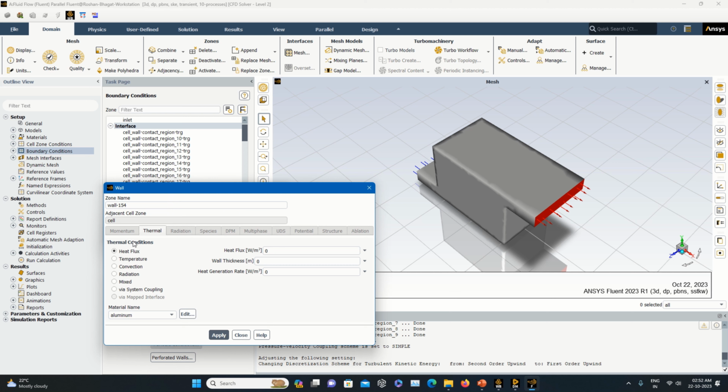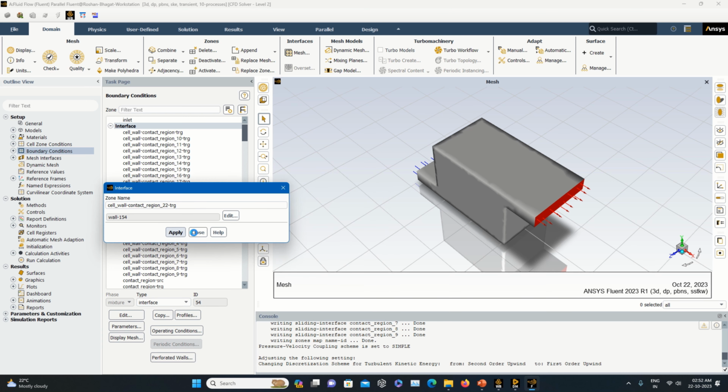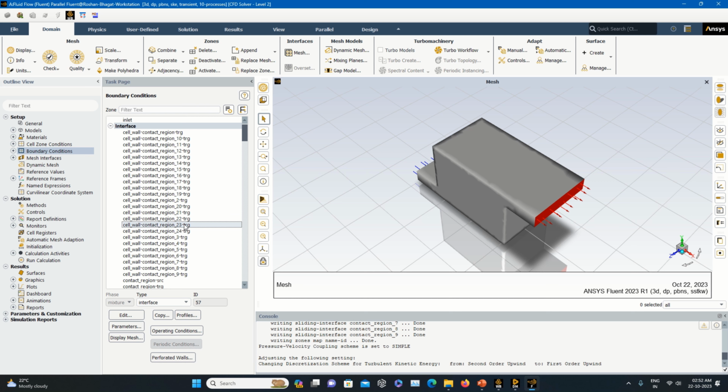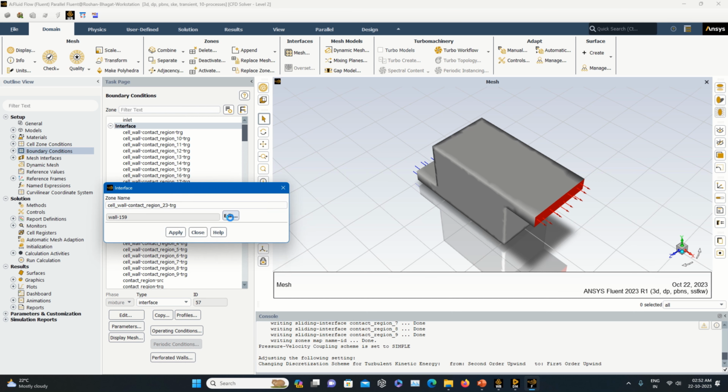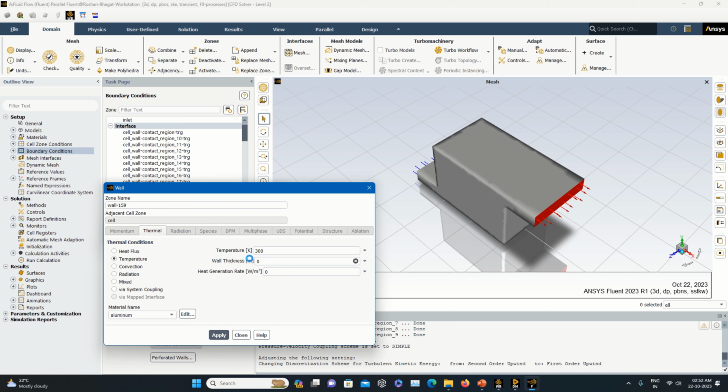So you could have done this with a finer mesh size also, but I will just check how the simulation proceeds, and if it is satisfactory we can go back and define the mesh again, and we can update the solution. So that is one way of reducing the time required. So at least for the trial run we should understand whether the simulation is going in the right way or not.